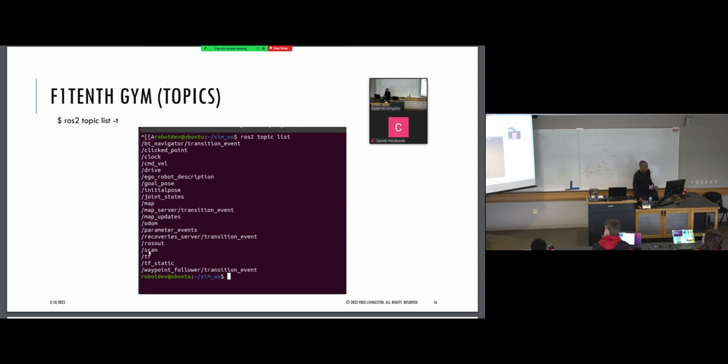And then your scan is your actual LiDAR. As it scans, it's going to have every XYZ point that comes back, like an RGB of a bunch of points coming back with intensities. And this would be your transfer function. We'll talk about that as well. That's a little bit of a description of everything that you could listen to or publish to in the ROS environment. For the odom, it gives you your X and Y velocity, is that right?